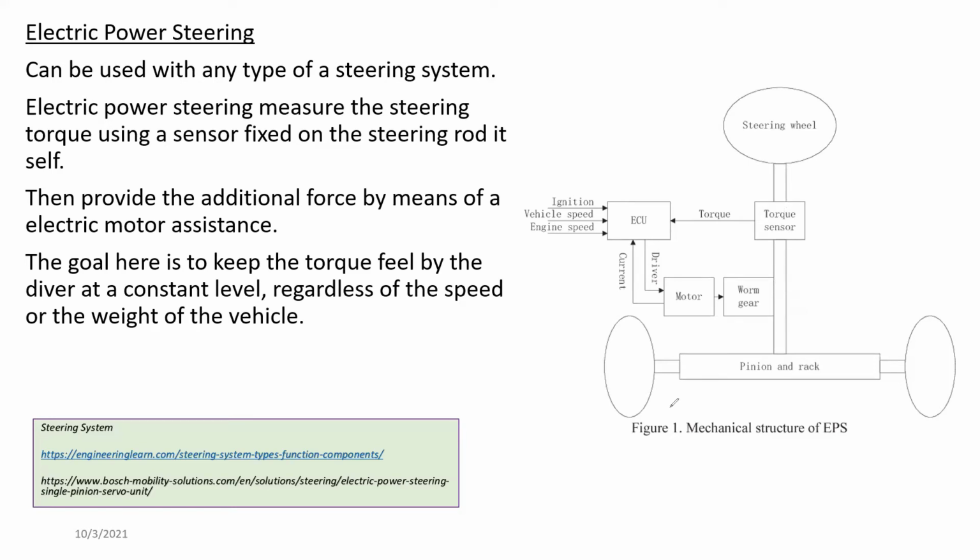Okay, so this pinion. Then this pinion and rack and everything is as usual. There's no difference. The same vehicle. So if you have a rack and pinion steering vehicle, the power steering conversion can be done without any trouble. But there will be some difficulty in some vehicles, some steering systems, because some actually need the ignition, vehicle speed, engine speed, these sort of details, right?